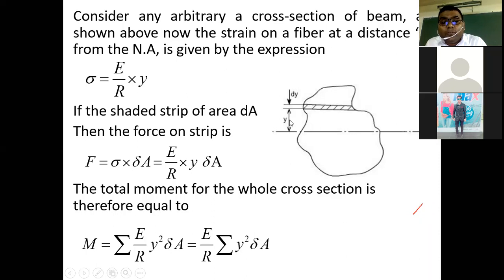This distance is y, so y into y becomes y square, and this is the force acting on the small area, and if you take the sum of that, it is the force moment acting on the whole area. So the sum symbol comes with this concept.